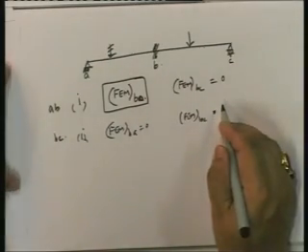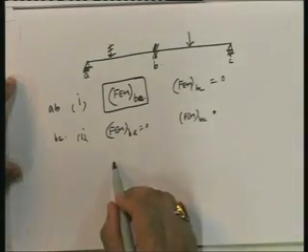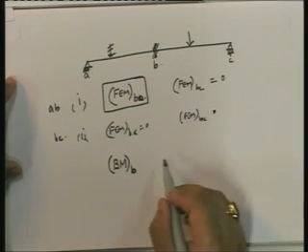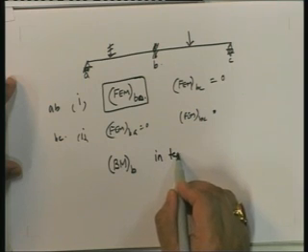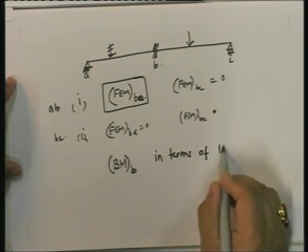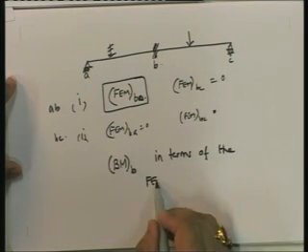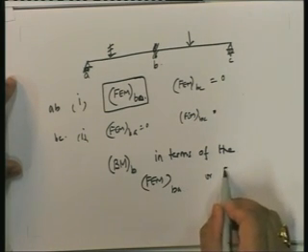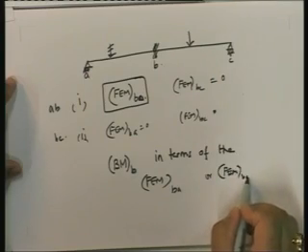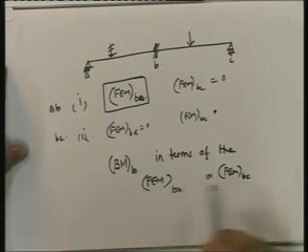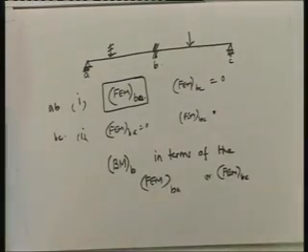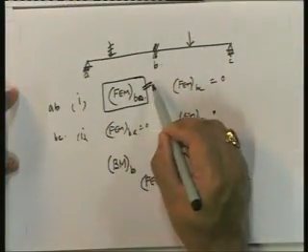And the point here is, if you could somehow find out the bending moment at B in terms of the fixed end moment, either BA or BC, depending on where the load is. Then you see, can I find out the fixed end moment given a load? Fixed end moment, I can find it out.